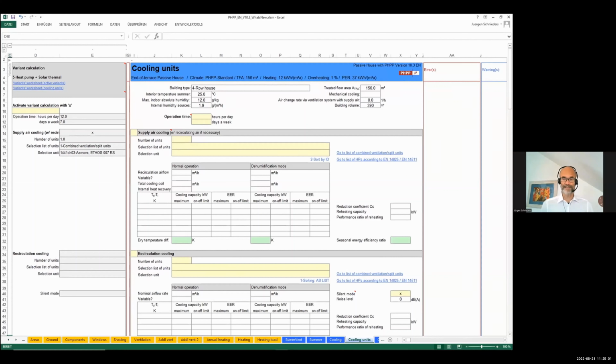And number two is that there have often been cases when the cooling system was not sufficient to provide both cooling and dehumidification appropriately, which can be the case in reality. So if we have a split system that is just moving a lot of air and is providing very little dehumidification, but we mainly have a dehumidification load and not so much a sensible load, then there is a problem and that needs to be shown.